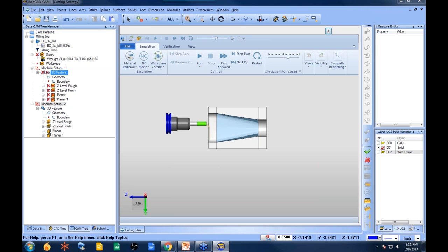The top view matches the top view of the world coordinate system. That's what it matches. So when you're on one side of the part or another side of the part, it shows which side it is in reference to 0. If you want to eliminate that, you can move your part to 0 and then have your top view align with your part, and then when you go to simulation, everything else aligns.